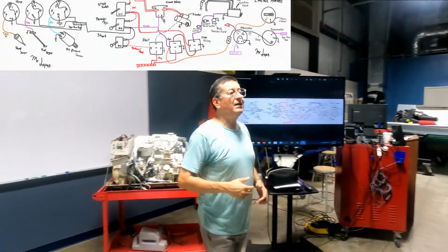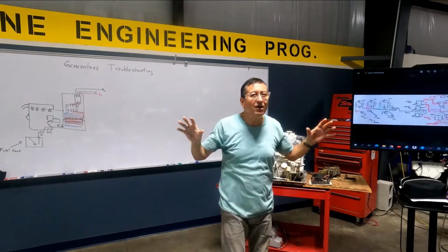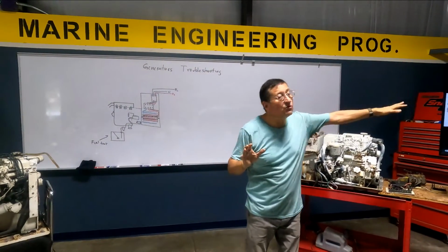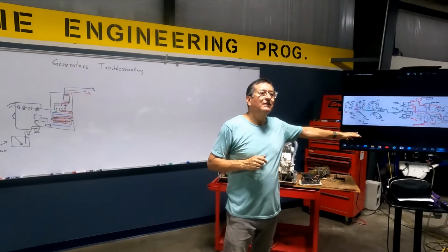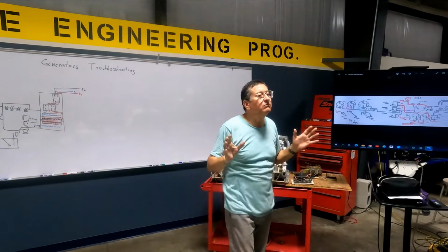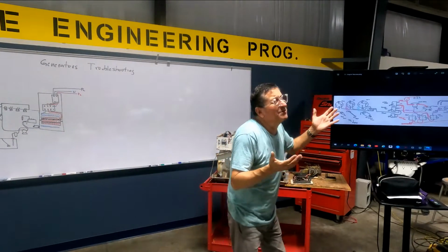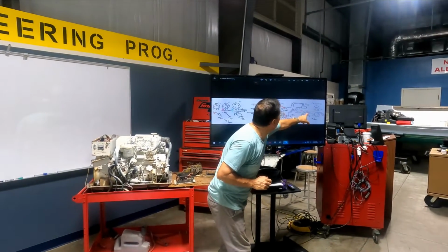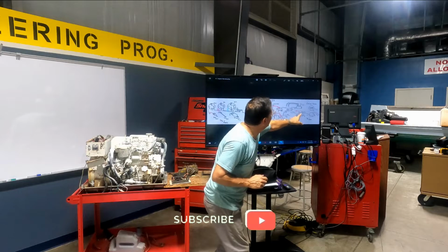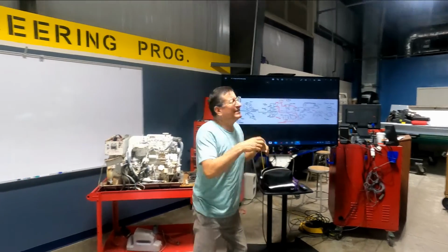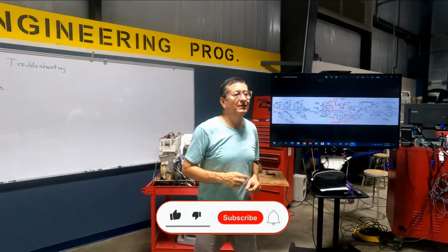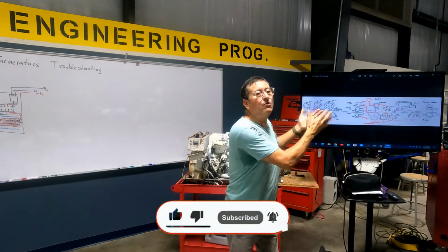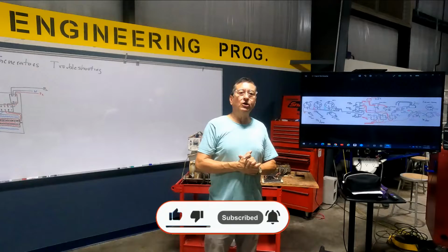The harness of the engine is totally AC or DC? It's DC. You have AC current in that harness? No. Tachometer signal? Oh, the tachometer signal, but this is the small AC output produced by the alternator that enters the tachometer. But this is not considered AC current. No, it's not considered AC current wiring. It's a DC wiring. Good?